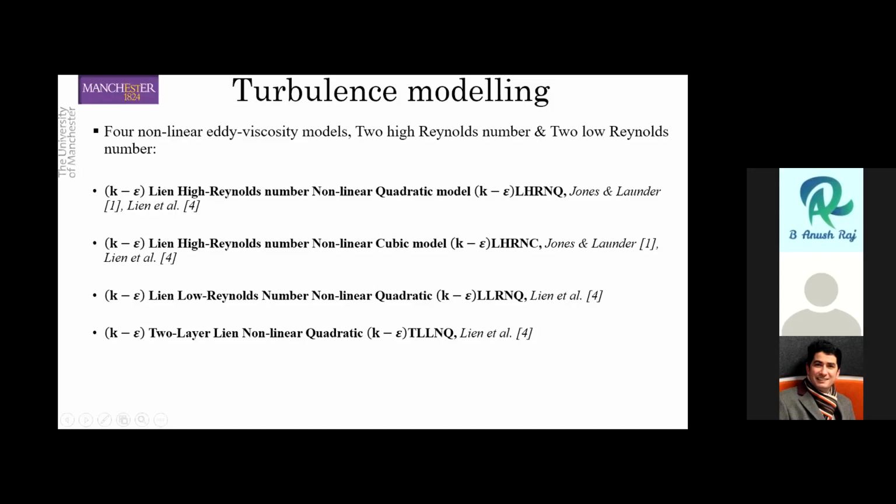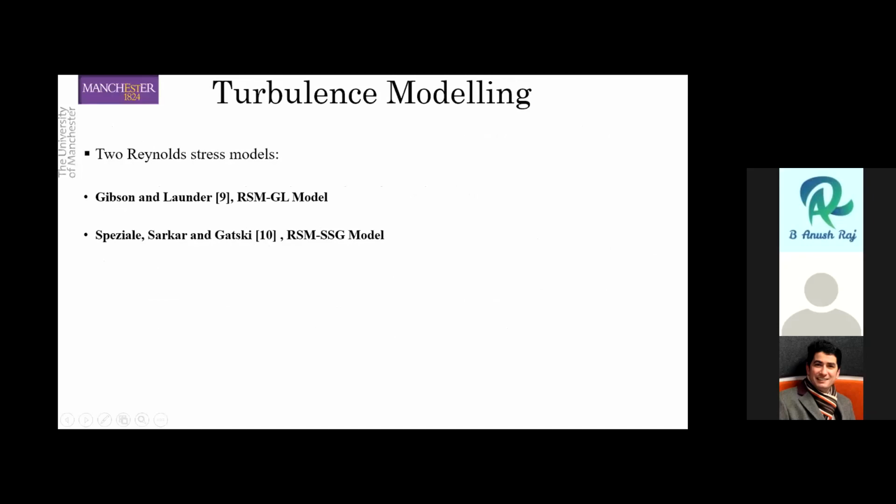The quadratic and cubic nonlinear eddy viscosity models account for anisotropy and sensitize the model to streamline curvature and rotation, which we have in this study due to the curvature of the blade, of course. And also, these models for the Reynolds stress naturally account for anisotropy influence due to rotations and streamlines.